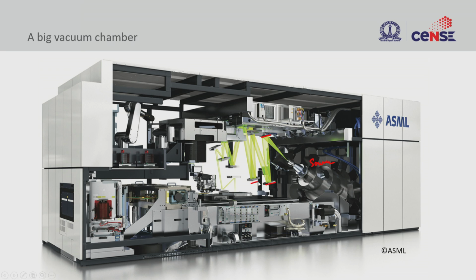This is all beam optics, trying to expand and then profile the beam so that we could expose the mask. There should be a uniform exposure of the mask, and once it is exposed, you also require optics in order to get it to the wafer. You can see here the complexity in getting the beam to the mask and also onto the wafer.